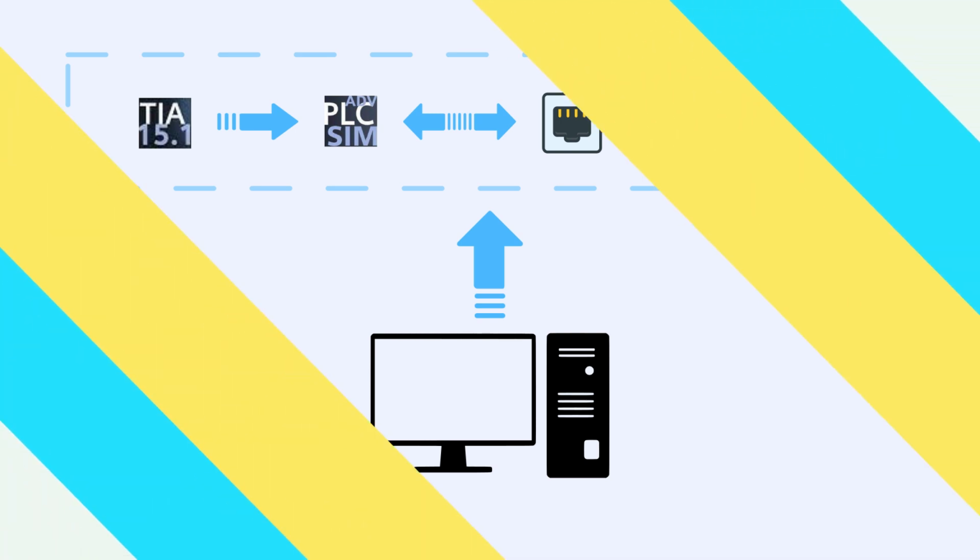The option of having a web server integrated into a PLC is a great advantage since we could access our server through any web browser, and in this way our variables can be displayed and controlled by any device within the network and without any additional software. It should be clarified that this option is not a replacement for HMI devices, because HMI devices are more robust and their integration turns out to be a little easier.